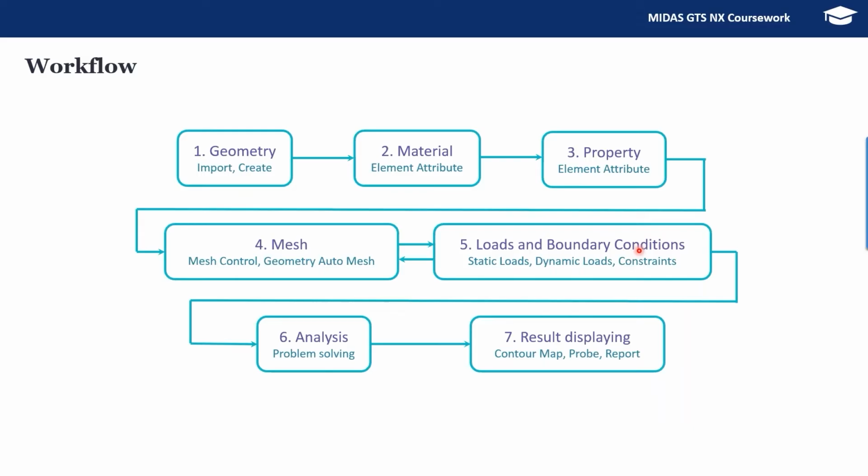You have been seeing this workflow from the starting day. Still, I would like to provide you with this workflow, because all the important steps which we take here, like all the trainings which we provide, pertain only to geometry in most of the cases. But the next steps, the material property and the mesh, are simply procedures. Once the geometry is completed, you can carry forward with the procedure of material followed by property, followed by mesh, and loads and boundary conditions and so on.